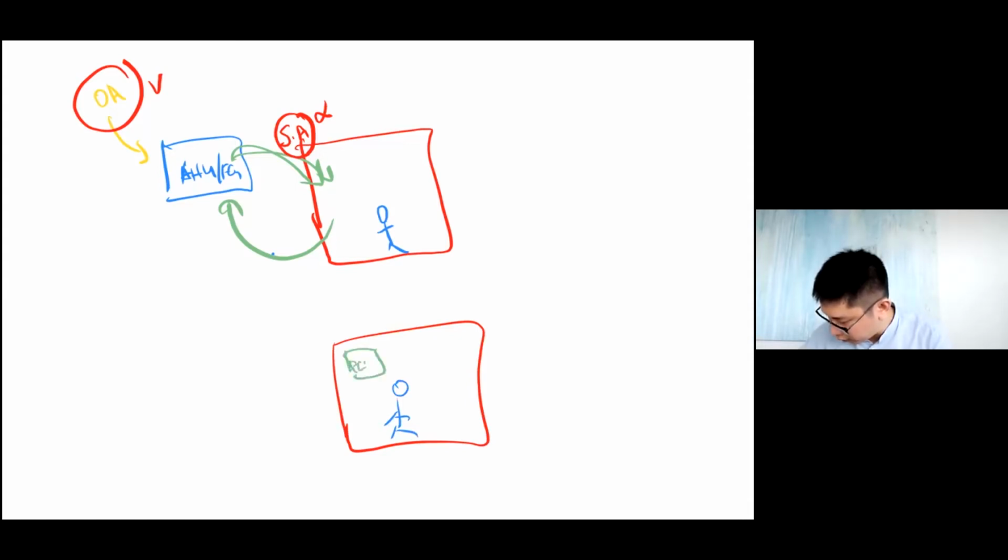an FCU serving the space, so supply air and return air. And you have OA being brought in. In this case, this is also considered a single zone. Whether the OA goes in directly, treated or non-treated, or goes into the FCU and is supplied to the person, it is the same case. So this is a single zone requirement.